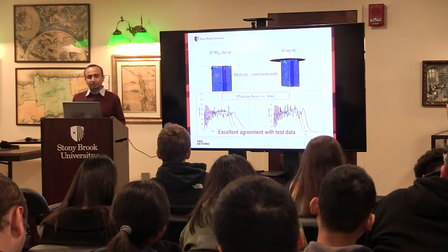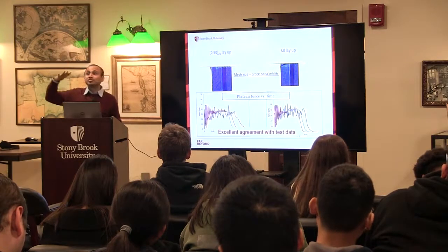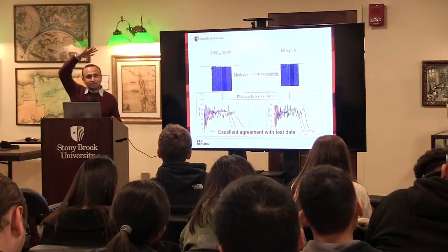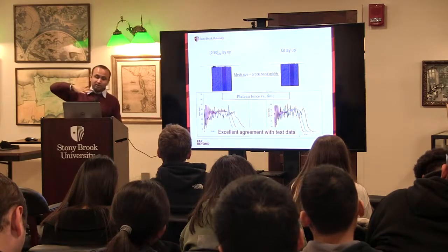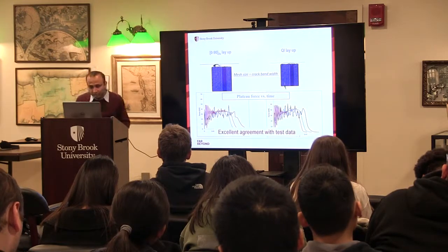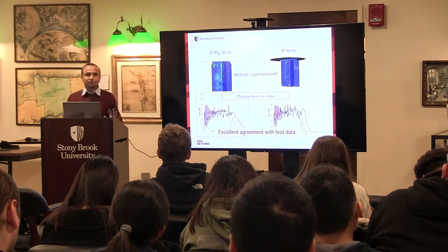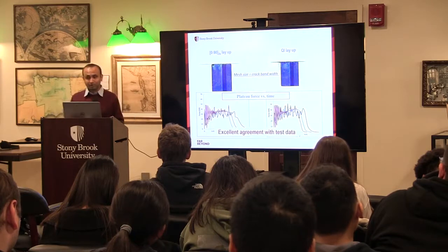If you notice, as it crushes, it is a progressive crushing. So it starts at the top. By the way, the crush can is impacted by a plate. It starts crushing at the top and progressively crushes the whole can. This whole event is taking place in less than 1 millisecond, so it is significantly slowed down here.